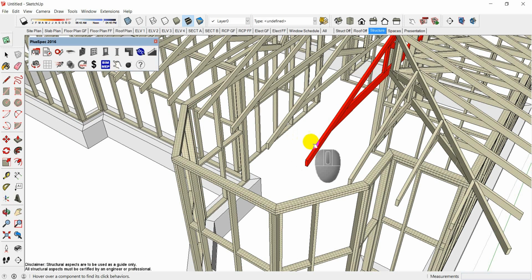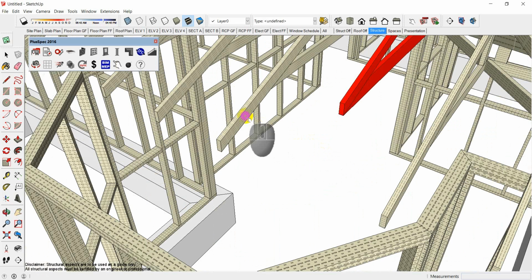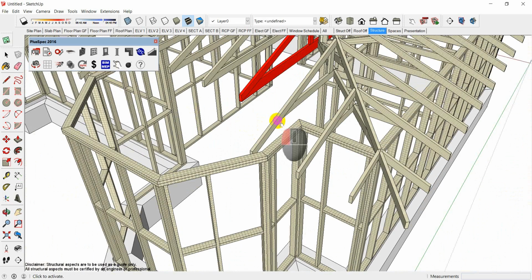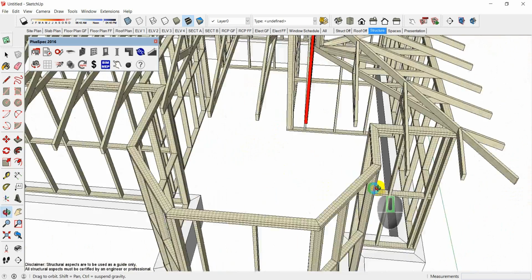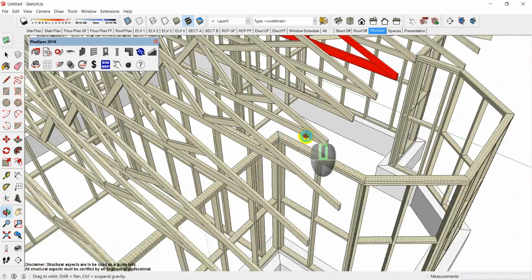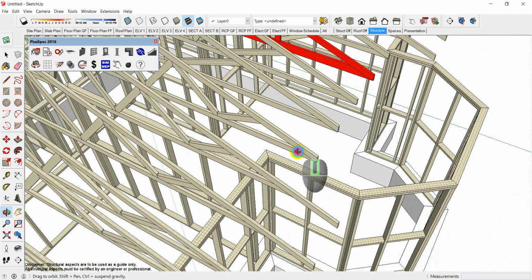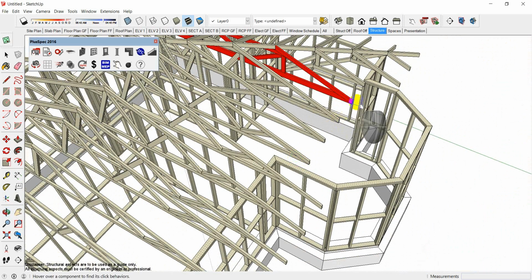Basically if I click here, you can do this on sort of any computer. Obviously, like tools, the more you spend on them, the better they are. Okay, and I can have a set of saddles going back up here, and I could pitch this here if I want to. Depending on yourself and how much work you've got on, sometimes it's cheaper just to pitch these kind of things out of stick timber than it is to mess around with a set of trusses.